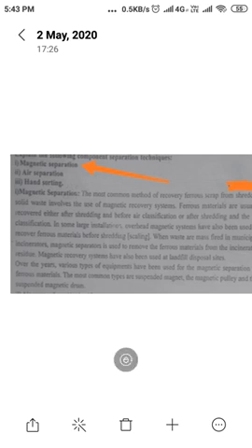In this, the classification has been used for a number of years in industrial operations for the separation of various components from a drier mixture also. In this solid waste, air classification is used for separating the organic materials, called the lighter fraction, from the heavier inorganic materials, which is the heavier fraction. Practically speaking, this involves the separation of the paper products, plastic materials, and other light organic materials from the shredded solid waste.